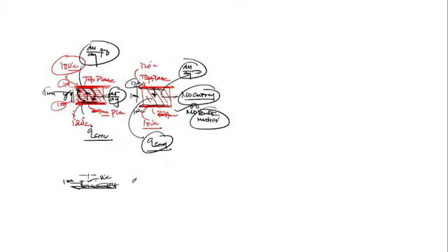Then what is dT upon dy? Then dT upon dy is, what is the temperature difference? Minus 20 upon 1 degree Celsius per millimeter. Yes or no? This is the temperature gradient. Means at 1 millimeter distance the temperature drops by 20 degrees Celsius. This is the temperature gradient. Yes or no? This is the case when the fluid is assumed to be stationary.